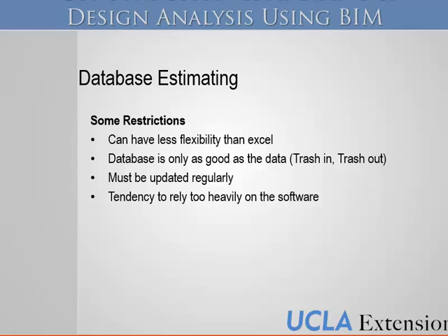Yeah, so that's a very good point. On every job, there's something called a schedule of values. The schedule of values is what the project manager gets from his subcontractors, showing what it actually cost. It's broken down into different categories, whether it's parts of the building or parts of the construction. For instance, your concrete guy's schedule of values is basically his bill. It'll have how many concrete footings and what that costs, and then how much slab on grade and what that costs.